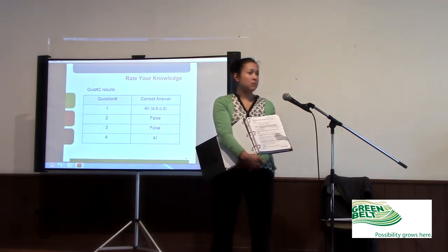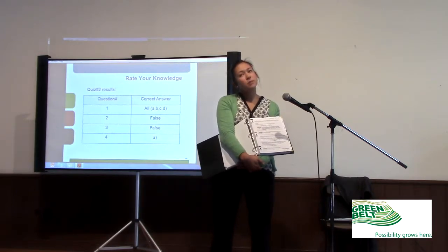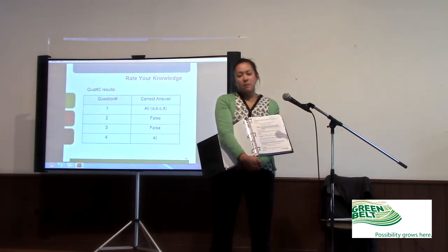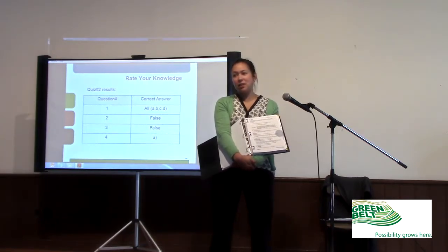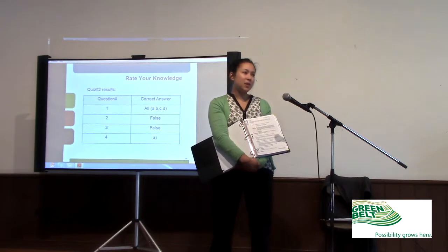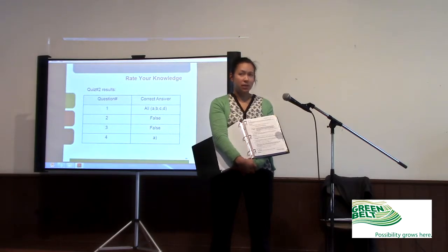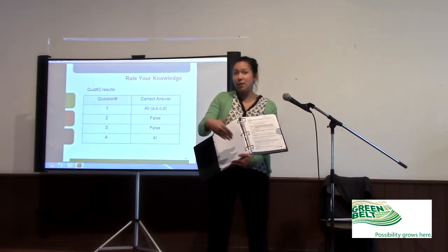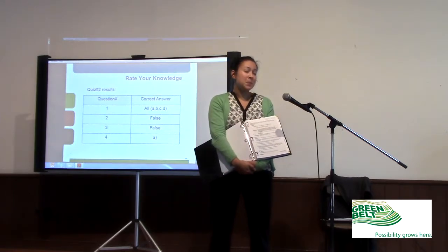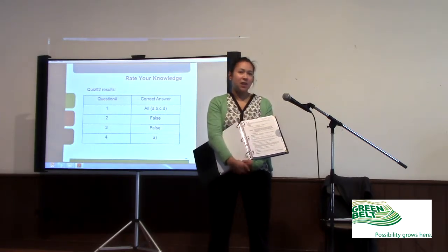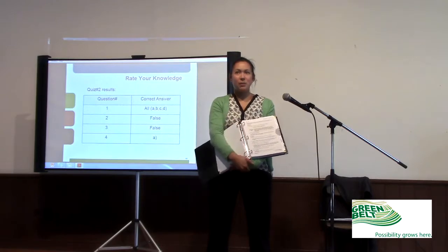I guess you kind of addressed it as far as what you see as an auditor, some of those things. The biggest thing I see as an auditor is people getting confused on where they need to take their test from and when they need to get their tests, or not getting that first test before the first start. You're supposed to test it before you start for the first time, just so you know that you're starting with potable water. That timing is difficult. And because it's a generic program, right now it says 2 tests for everybody, even if the season you're using the water for is only 3 weeks long.